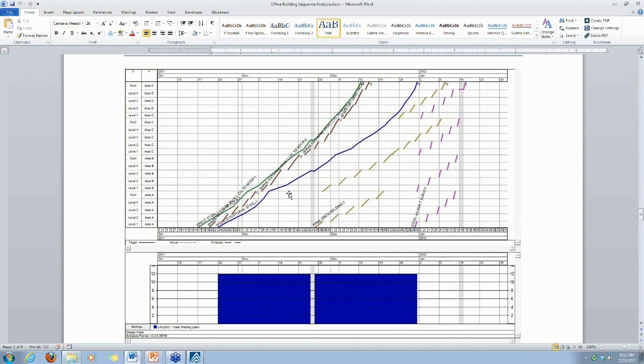So this was another option that we provided as part of our analysis, if we really wanted to streamline the welding, and in fact, if we simply couldn't get more than 12 people for this welding. Let's say it's some specialty welds and there's not that many guys in the area who can do it. Reducing that peak resource count from 18 down to 12 would be a good decision. What it means is that you have to activate 12 guys early and try to keep them as continuous as possible through the job, which is represented here by this continuous resource graph for this activity.